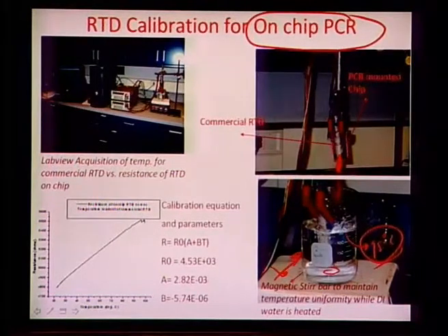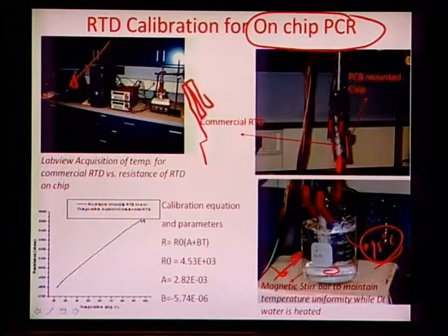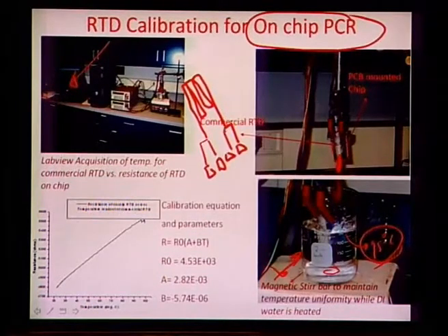In the meantime, the LabVIEW based acquisition system, as illustrated here, takes the data from the 4-wire thermocouple, the 4-pointed probe thermocouple, and the serpentine heater, which is also in the 4-wire configuration within the microchip. Essentially this is a voltage divider kind of circuitry where you have readouts from these two and voltages given to these two, and this is also used to avoid contact resistance.